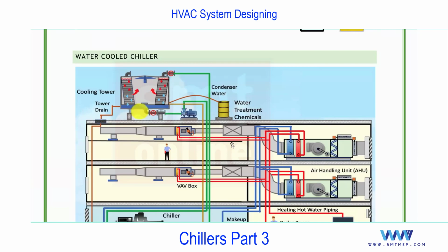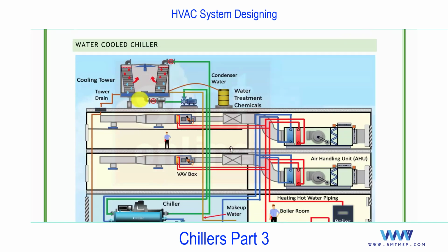In some projects, we need a soft water plant, a dosing plant. If you are getting hard water in your location, say a TDS level of 2000, we can consider it as hard water. So to convert that hard water into soft water, a dosing plant or a softener is required. Or else the life of the system will reduce. This is also one disadvantage, but we have some more points.